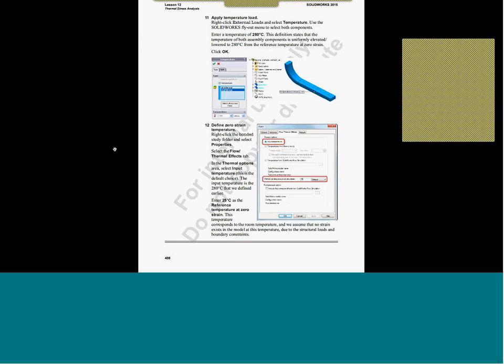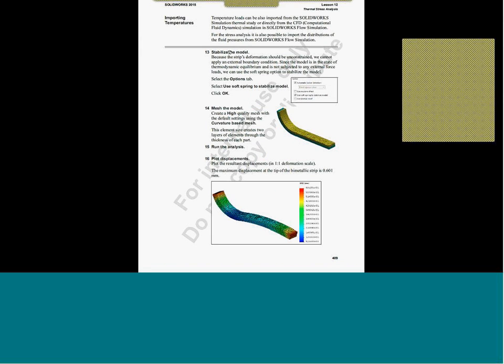Anything else? Stabilize the model. This is what we discussed yesterday. In this particular model, if you observe, there are no restraints. They are not holding the model anywhere, and only soft springs are being used to stabilize it.